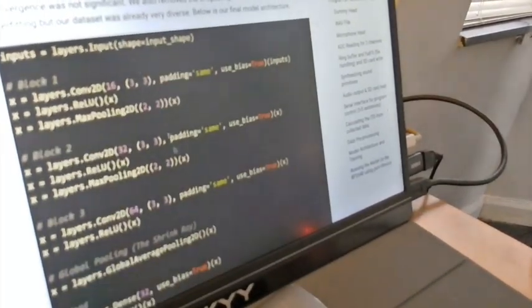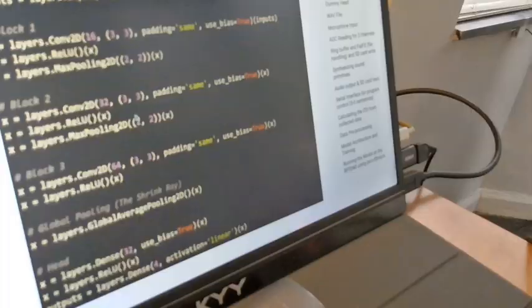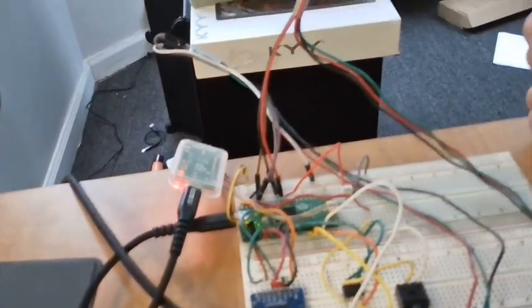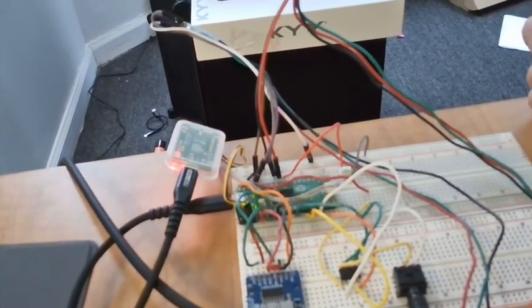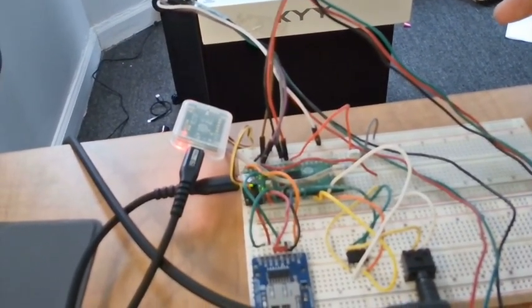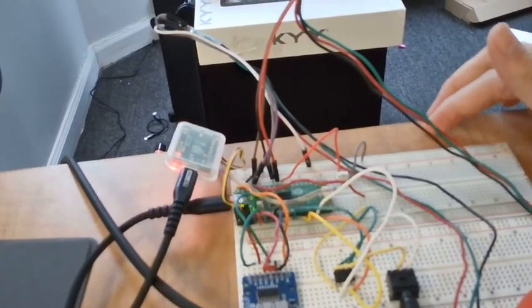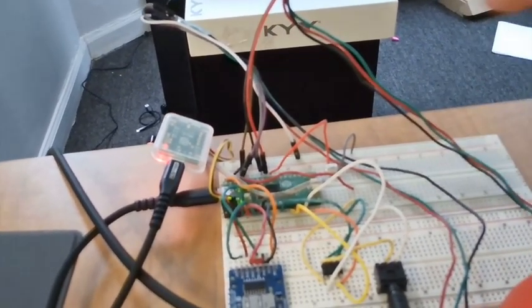And we actually had to remove some of the initial operations since after trying to load up the model on the RP2040 using the TFLite Micro library that Raspberry Pi made available to run TensorFlow models on microcontrollers, we realized that some of the operations that we used, namely the Leaky ReLU, were not available. And we also had to remove batch normalizations since they incurred a bit too much memory consumption during inference.